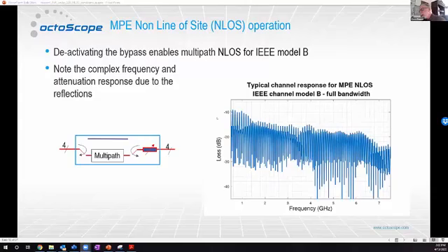Part of it, I think, to be honest, is the measurement capabilities of the test instrument. So we're looking over a huge frequency range here, and sometimes these nulls are so narrow that they kind of get lost in the quantization of the measurement instrument. If you zoom into these things, you probably get a better picture.